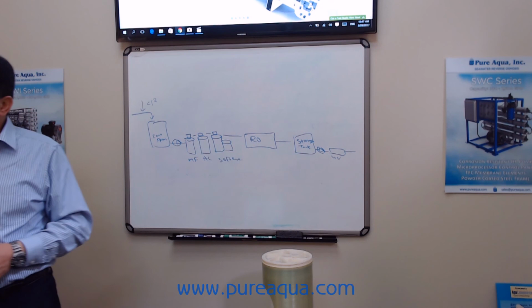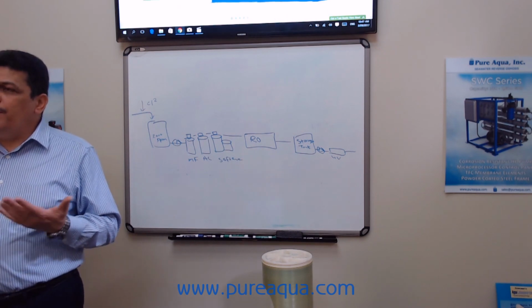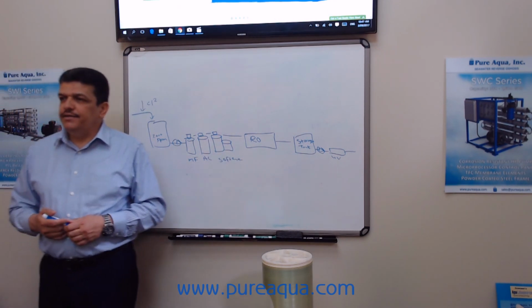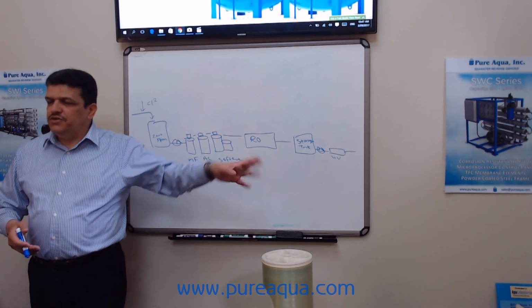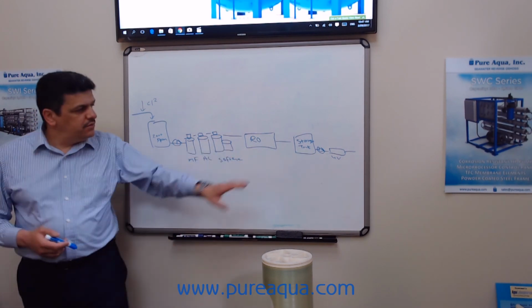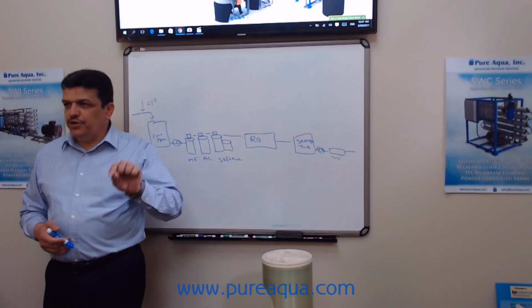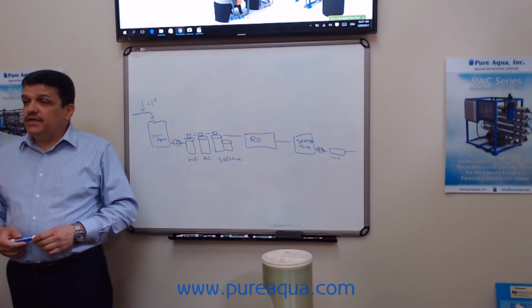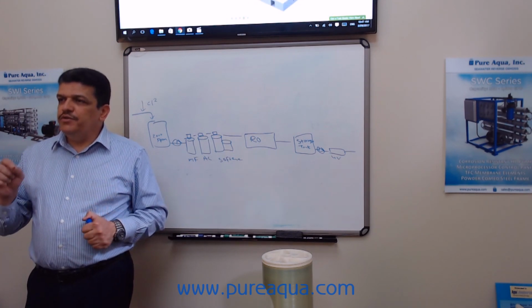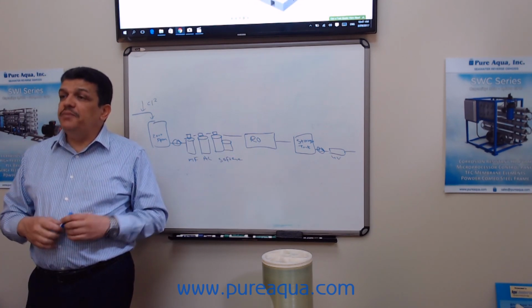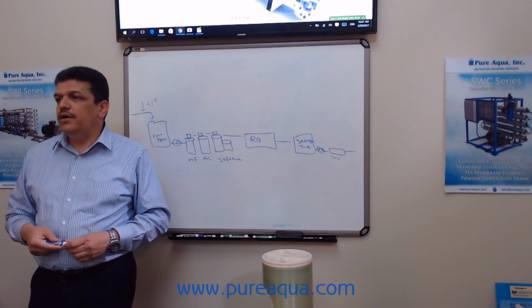Now you can ask a question. How much time is this water going to be stored in the tank? Is it an hour or 2 hours? Okay, I'm going to use it, so it's okay. There is no need to do any chemical dosing here, which is a chlorination. If you think that the water is going to stay more than 24 hours in the tank, you need to dose a little bit of chlorine to prevent any upcoming bacterial growth in the water.